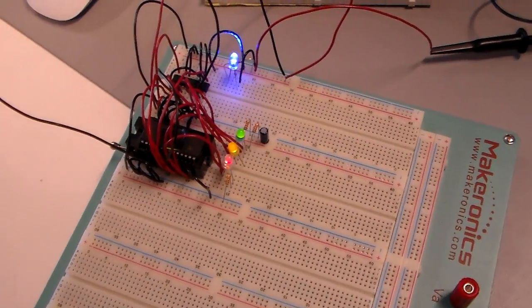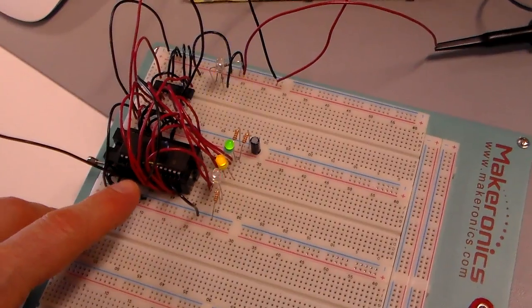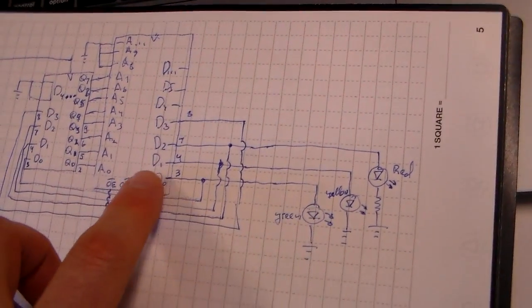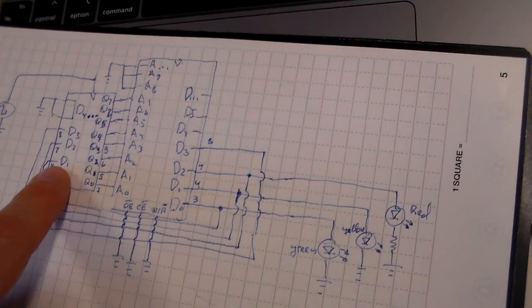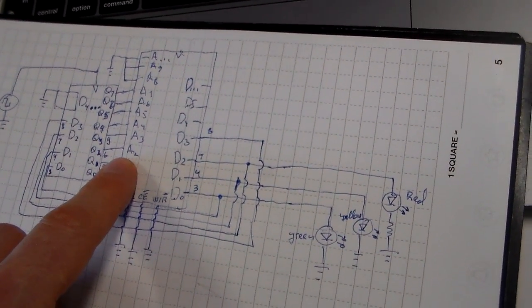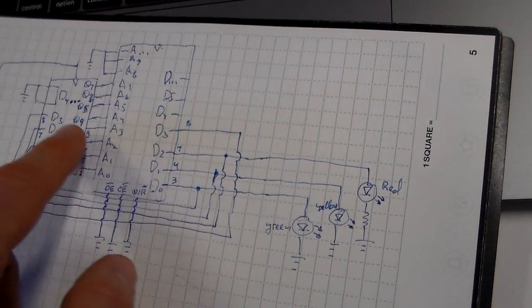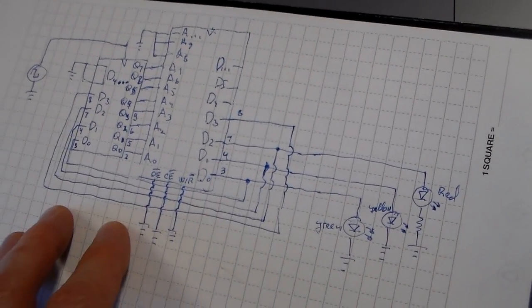This is a video showing a finite state machine, which is, in this case, implemented by a ROM memory chip with data programmed into it. And the way this works is we have the data line output from the ROM chip recycling back around through a flip-flop, a D-type flip-flop. So basically every address that's called up, the data read from that address location becomes the next address. And by doing this, you can program all kinds of interesting and arbitrary sequences.